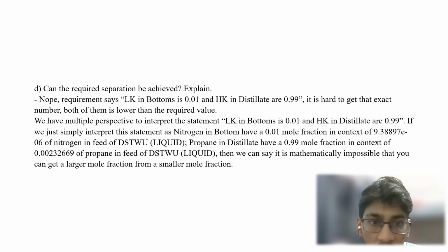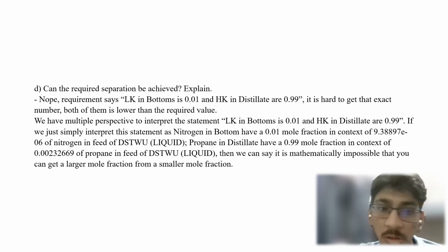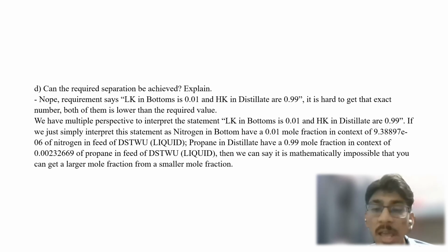Okay, for the first part, the required separation cannot be achieved as per the given conditions. The specified requirement for the mole fraction of the light key in the bottom is 0.01 and the heavy key HK in the distillate is 0.99.